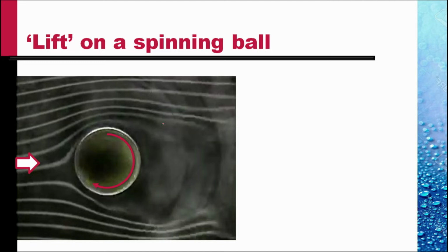And therefore, the pressure at the top is less and the pressure at the bottom is more. Because of this, the separation points shift more to the right on top and more to the left on the bottom, and this gives you a force which is upwards.